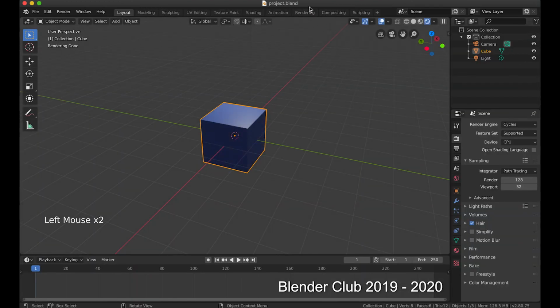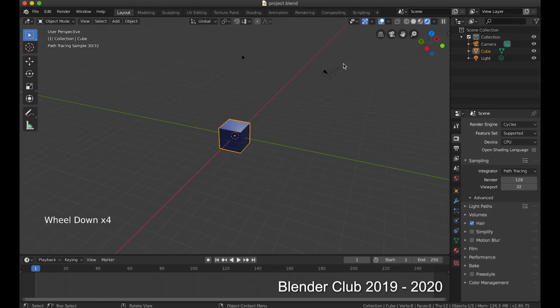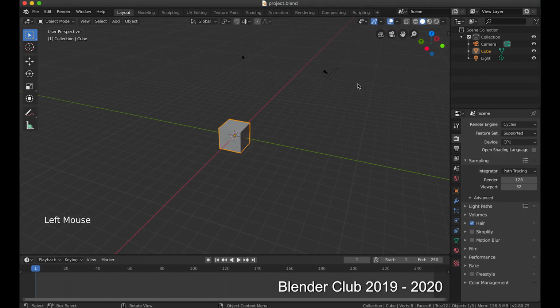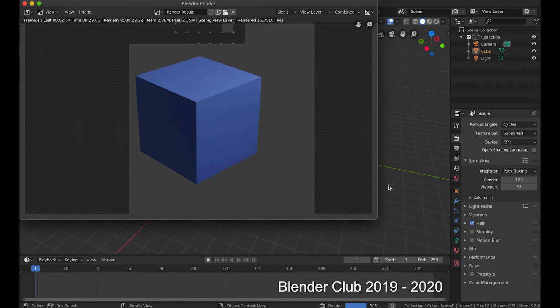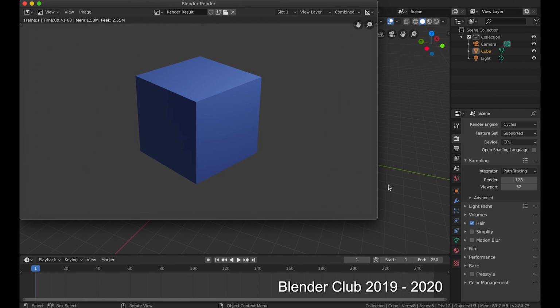While the project is saved as a .blend file, images and animations must be saved as JPEGs, PNGs, AVIs, MOVs, etc. This is accomplished through a type of exporting called rendering, which is just the process of simulating and collecting mathematical rays described earlier. To render an image, go to the Render menu and select Render Image. This will export an image of the meshes from the camera view as lit by the lamp using the selected render engine. This image can be saved from the Image menu in the pop-up window.